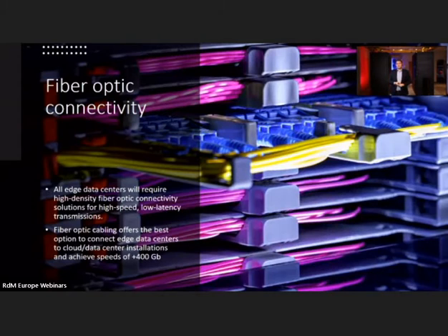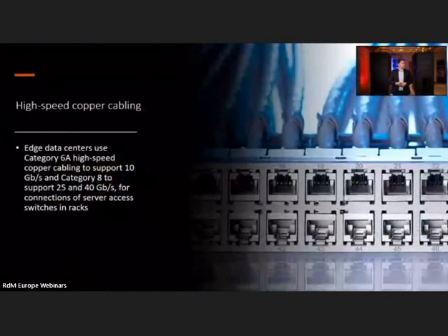Of course, there are some limitations due to the length of the fiber and due to the attenuation in the link, but every application has its own requirements. Usually we can find such requirements in the description or in the datasheet of the active device or the transceiver. You can find the maximum attenuation possible in the link, the wavelength, the fiber type, etc. So it is necessary to look at that every time a new device is implemented.